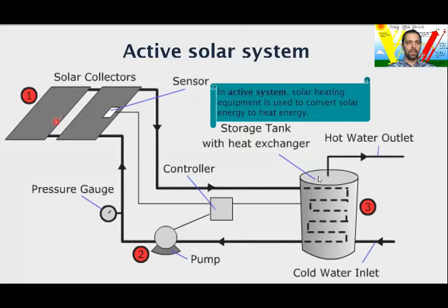The flat plate collectors are usually placed on the roof or ground in the sunlight. The top, or the sunny side, has a glass or a plastic cover to let the solar energy in. The inside space is a black absorbing material, actually, to maximize the absorption of the solar energy. The cold water is drawn from the storage tank by a pump through the flat plate collector mounted on the roof of the house. The water absorbs the solar energy and returns back to the tank.